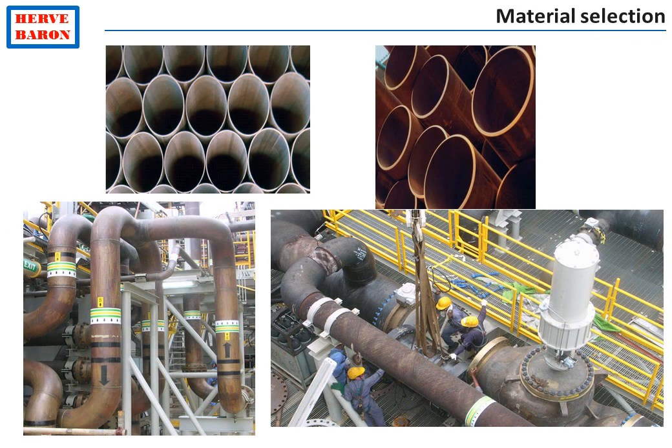A large variety of materials of construction are used in oil and gas facilities. It includes ordinary carbon steel, as well as special types of carbon steel, such as low temperature carbon steel. Also, carbon steel can be used as galvanized carbon steel or with other types of internal coatings, such as cement or rubber lined. It includes as well what are called corrosion resistant alloys, which are stainless steels.